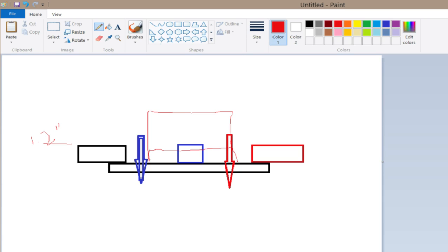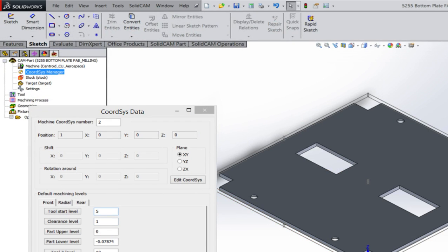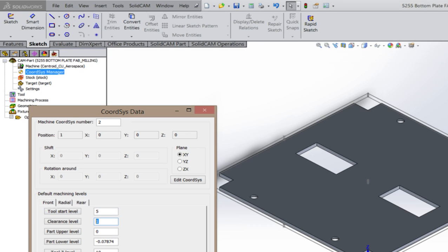That's a very common mistake, and it's called a crash, because if you slam into that and the tool's big enough, it can knock the head out of alignment on the machine. Okay, so you need to set these properly. If I was on those two big bed mills, I would set them at 5 inches. There's pretty much no chance that I'm going to have clamps on this particular piece that are going to be taller than 5 inches. Okay, so that's pretty safe. If you're on Wolf Creek, you're going to have to do something lower than that, maybe 2 inches, maybe 2.5 or 3.